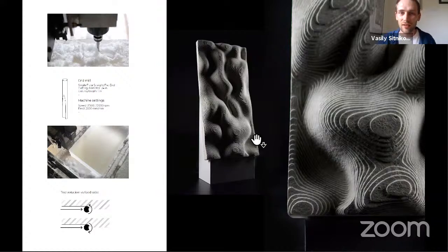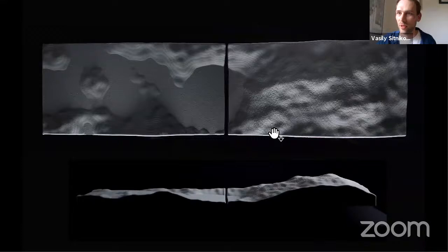And in fact, it was also quite an easy way because ice is easy to CNC mill because it doesn't have any fibers. It's a homogeneous polycrystal that is brittle as well. So when you're milling it, it's kind of chipping and not heating up the tool, and you can go pretty fast through ice with the CNC mill, basically.